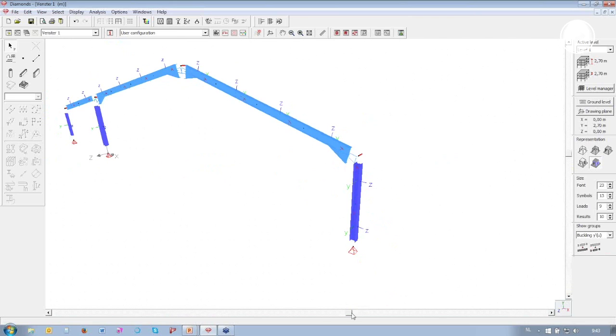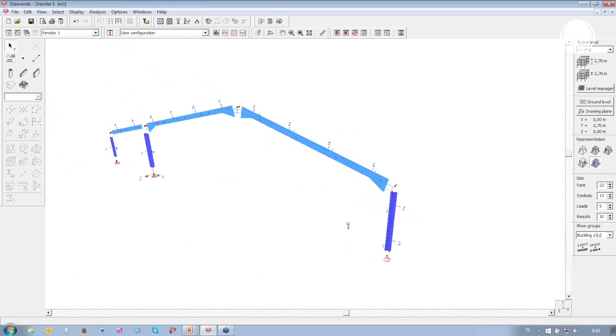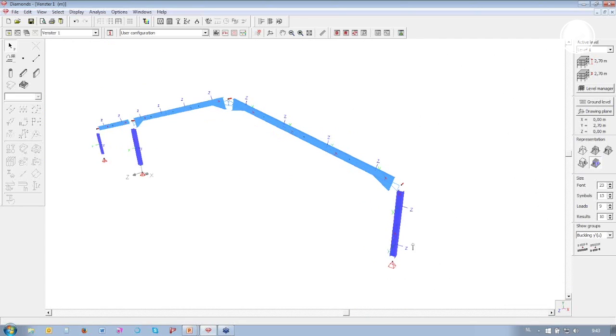So for buckling around the y prime axis, what I can see over here is that these elements are grouped together. That means that when they buckle to the left or to the right, they are acting together as a whole, which seems logical also for these elements. When they could buckle to the top or to the bottom, they will behave as a whole, as one element. And I think for the other elements, the definition is okay.